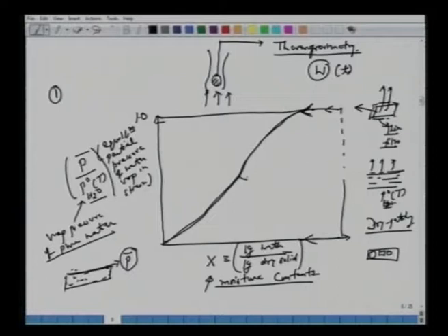So let's say this is wood. Wood has a very typical feature that for a long time it soaks a lot of moisture. So for a long time, as the moisture content decreases starting from certain values, say 0.35 to 0.3, this partial pressure at the surface can be assumed to be the same as the vapor pressure of pure water, because it's a thin film here.